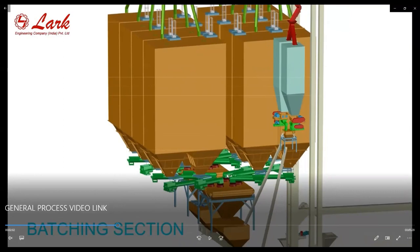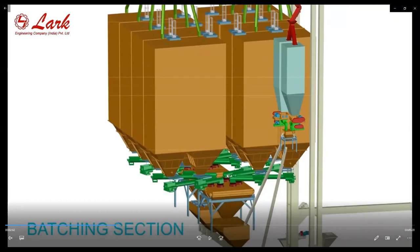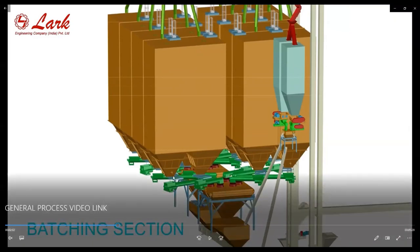We just have to select the recipe and the number of batches as per the formulation, with 0.25% accuracy tolerance. Automatically, the batch will come to this weigh hopper with the help of the load cell and these screw feeders.